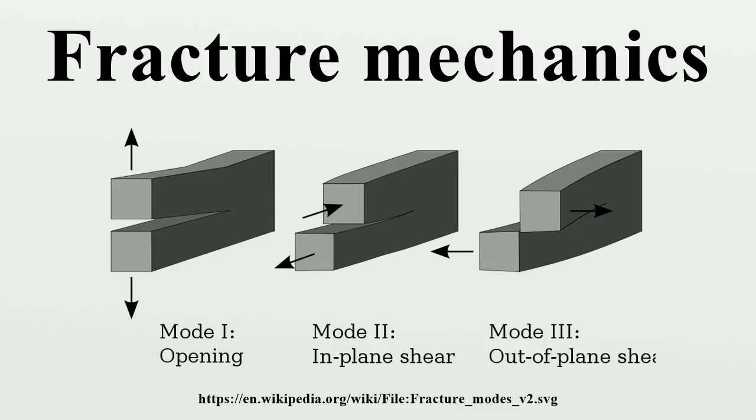Fractography is widely used with fracture mechanics to understand the causes of failures and also verify the theoretical failure predictions with real-life failures. The prediction of crack growth is at the heart of the damage tolerance discipline. There are three ways of applying a force to enable a crack to propagate: Mode I fracture, opening mode; Mode II fracture, sliding mode; and Mode III fracture, tearing mode.